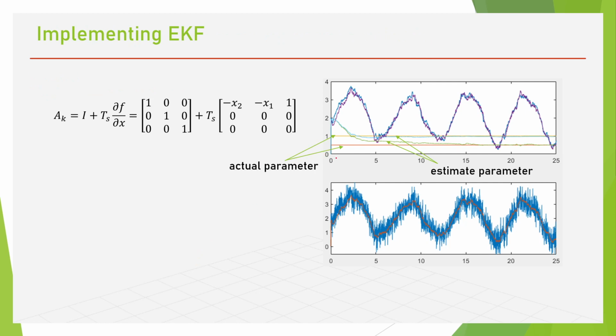Like here, first, this is the true state and the true parameters, orange and red here, straight because they are constant. In the Kalman filter algorithm, initially we estimate that they are all zero, but then it jumps like this, and then it converges to the true parameters, and the state we can also estimate at the same time.